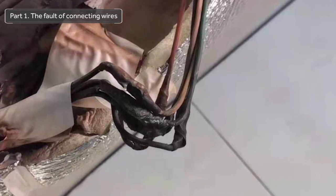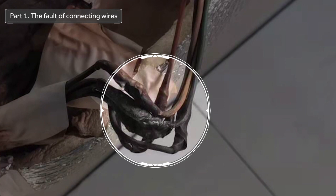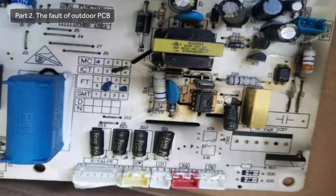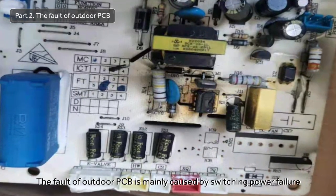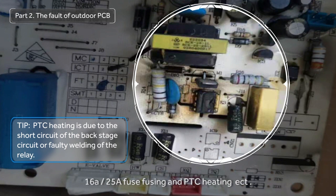Part 1. The fault of connecting wires. For example, wire joints get damp, or aging wire joints, incorrect connection, signal interference, etc. Part 2. The fault of outdoor PCB. The fault of outdoor PCB is mainly caused by switching power failure, 16 amp, 25 amp fuse fusing, and PTC